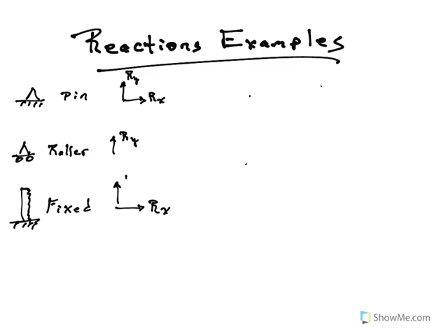vertical reaction. But then finally, if you were to push on this pole, let's say you push horizontally, generally speaking, it would want the pole to kind of rotate downwards, rotate clockwise or something. But it doesn't want to. It's cemented into the ground. So there's going to be like a rotational reaction called a moment reaction. And so there's also a moment reaction. So three reactions for the fixed support: the horizontal one, the vertical one, and a moment one.